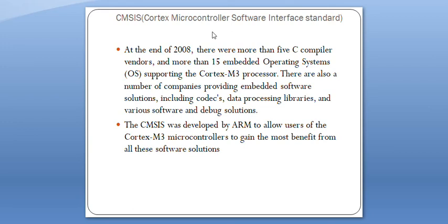So many functions like perceptron, or even back propagation, BNN architecture, can also be developed. And the requirement is that the hardware should be able to drive that software, which means the hardware should also be complex. It should not be an 8-bit controller as such. It should be a 32-bit controller with good performance, in the sense that the clock frequency should be higher.